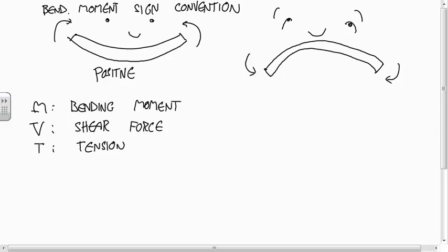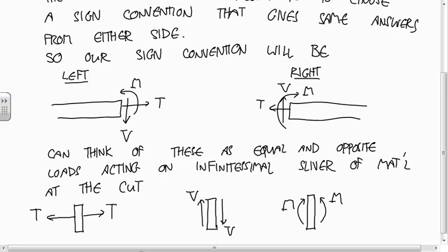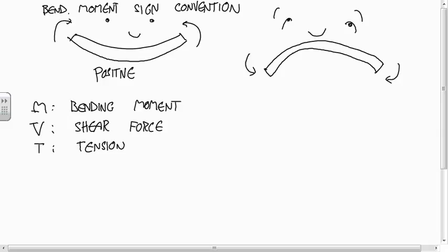And notice that if you have something subjected to shear force, that has the effect of deforming it in a shear deformation. So there's a relationship between these shear forces and a change in angles of this material. If you push down on one side and up on the other side, the effect is to change the angles.